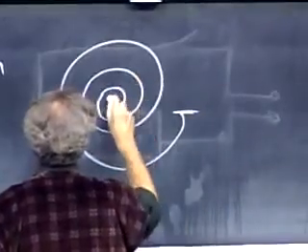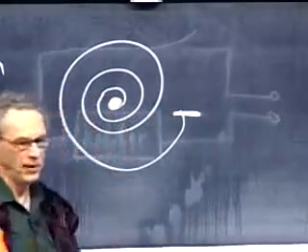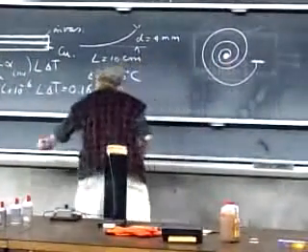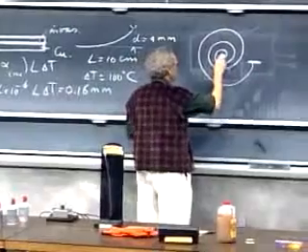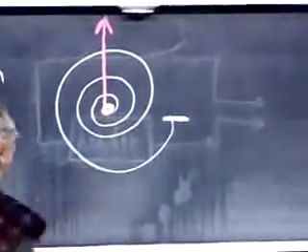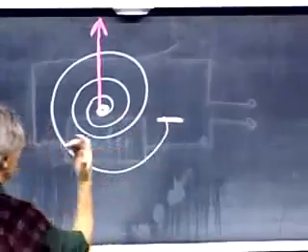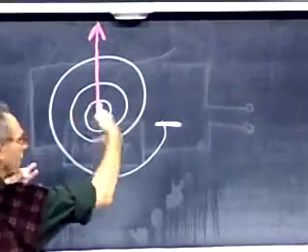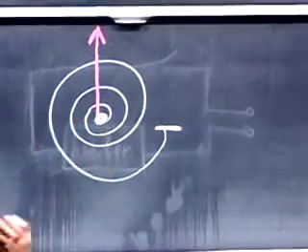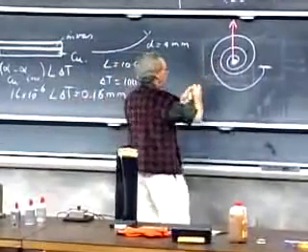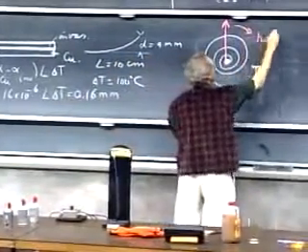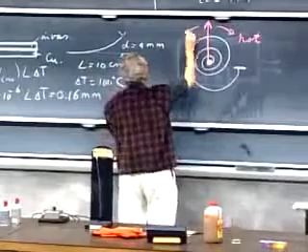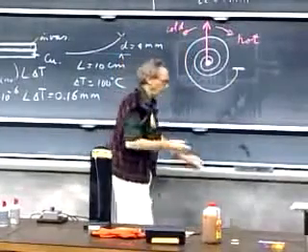There's a coil. This end of the coil is attached to the plastic casing. And here is the red hand. It's a pivot here. It's a red hand. So this is fixed. This cannot move. I heat it up. What will happen when I heat up? This is already a bimetal. It's already curved. But when I heat it up, it will tighten even more. It will curl up even more. And when this one curls up even more, it will go into this direction. So this is when the temperature increases. And when it, of course, gets colder, it will uncurl, and so here is cold. And that's what the whole thermometer is based upon.